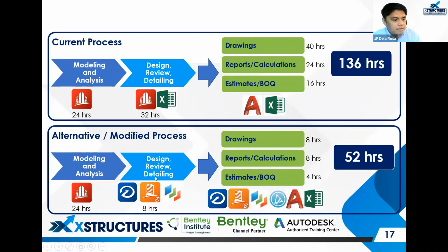And then for the drawings, we can reduce to only 8 hours, since all the drawings will just be extracted from the software itself. RCDC and RCDC FE can produce high quality drawings, which you can simply export, put on a proper title block, and that's it. You already have the final plan.